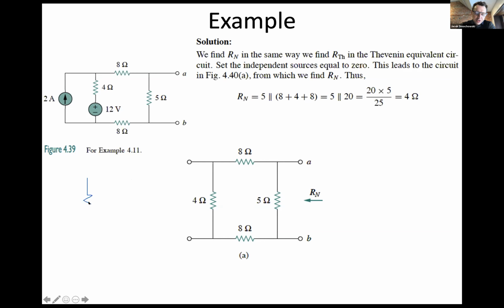But I'm going to show you that it still doesn't work. So this is the 12 that you're talking about, this is the 8, and this is the 5, right? The problem with combining them all is you are measuring the resistance between this point and this point. To go from here to here, you can still go only through the 5, and so it's still 20.